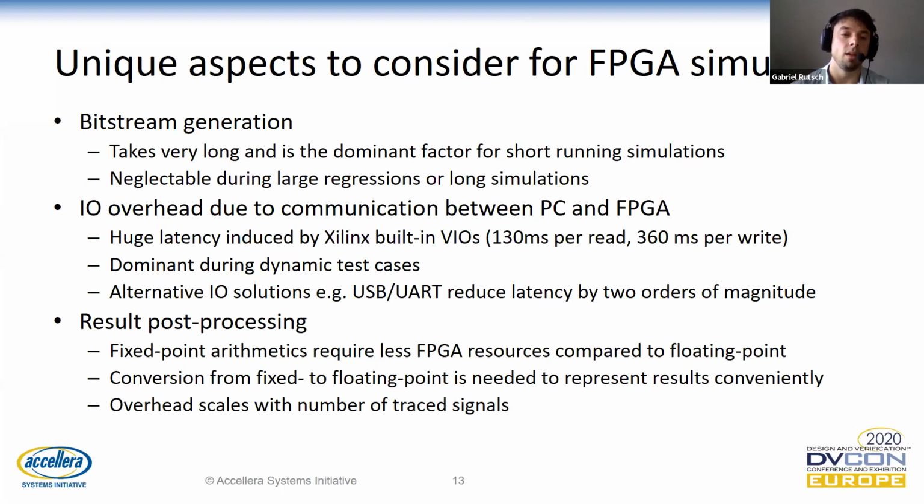Luckily, there's typically a set of alternatives available on an FPGA board. One of the most typical ones is just to use the USB UART interface. In our example, this already reduced the latency introduced by this additional communication interface by 2 orders of magnitude, which is great. And since we make use of fixed point arithmetic and also the simulation results are represented as fixed point data types, those are not quite convenient to interpret in the end. And it does make sense to do a conversion to floating point later on, which needs some additional compute time.